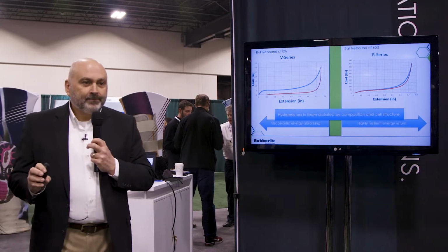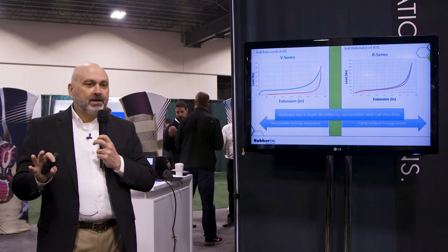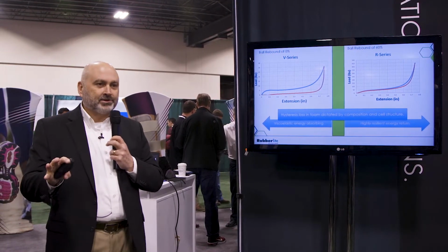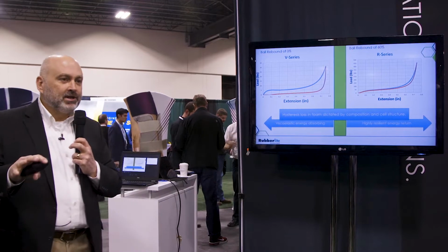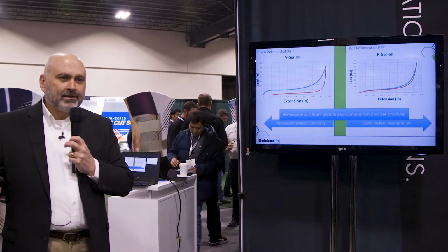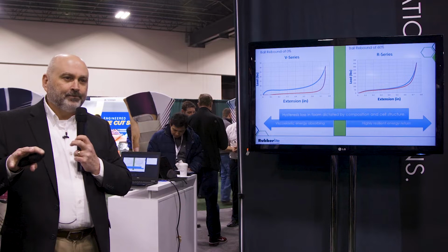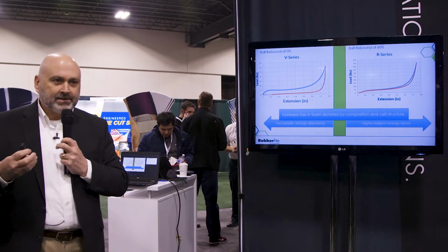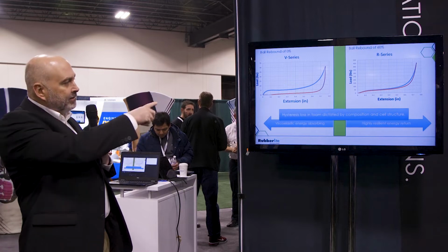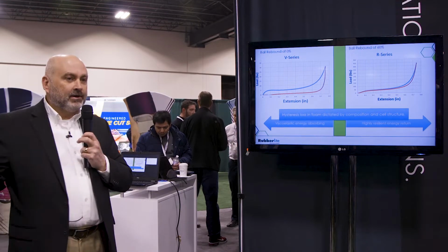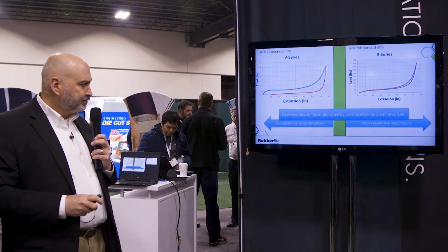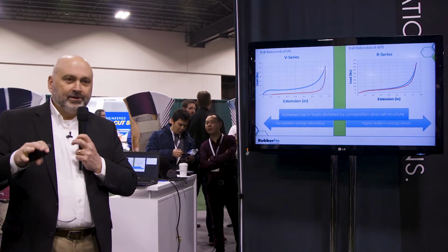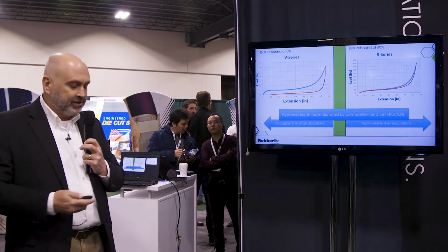So in foams, that is a complicated subject because you have both composition and geometry. You've got a cell structure. For instance, a closed cell material can trick you into thinking it's highly resilient, but it's that pneumatic effect of the air in the cells that's giving you that resiliency. Here in an open cell foam, which HyPUR-cel polyurethane is all open cell, you're going to have a durable product with a highly resilient return of energy.